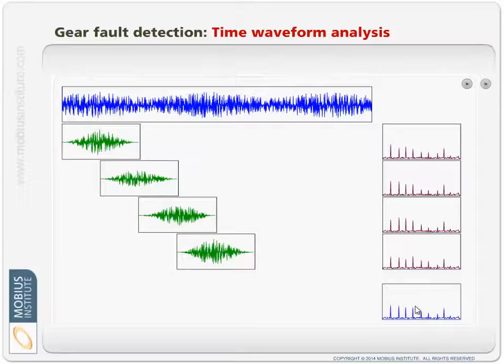So with normal vibration, this is just fine. There are limitations, and I've talked about those limitations in other webinars and certainly in our training. But the fact is that for normal processes, that's an acceptable process. But when you have more complicated vibration from a gearbox, all this windowing and averaging can really lose the information that we ultimately want to see.